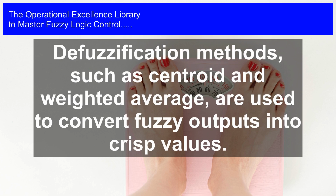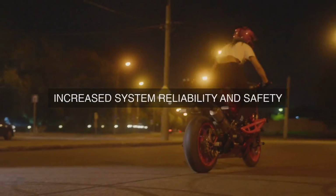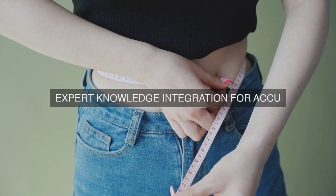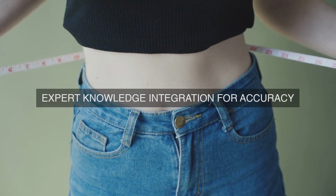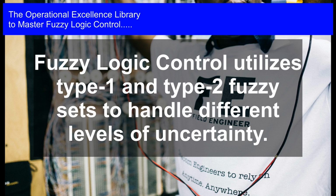Fuzzy rules can be combined using various logic operators, such as AND, OR, and NOT, to create complex rules that capture the relationships between the input and output variables. Fourthly, fuzzy logic control employs defuzzification methods to convert the fuzzy output into a crisp value. Defuzzification methods, such as the center of gravity method or the mean of maximum method, are used to calculate the output value based on the fuzzy output.